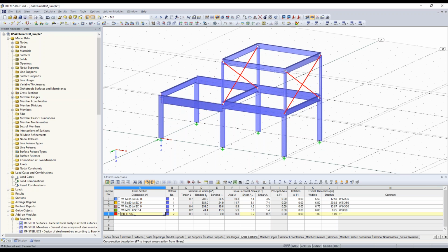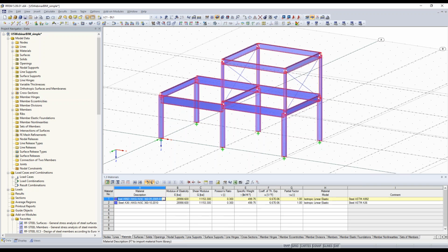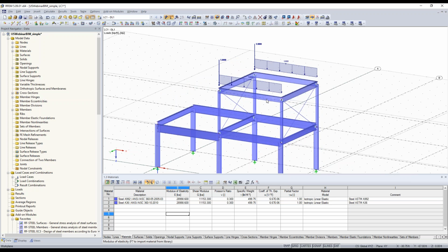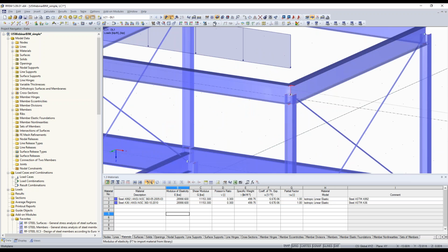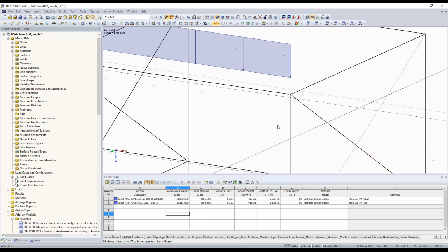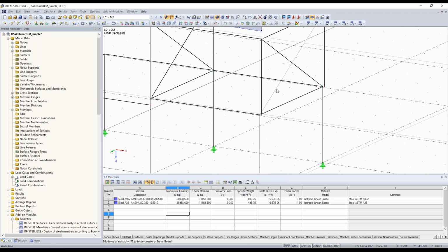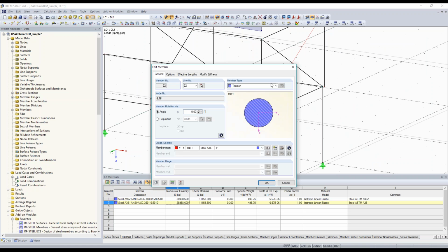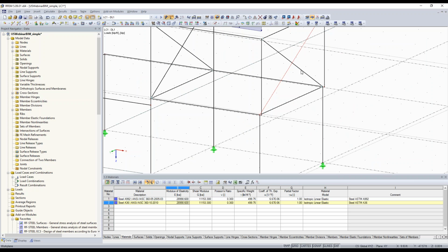So when I look at the materials, also steel ASTM was transferred to steel, ANSI AISC material, and same to ASTM. So with this, in the load case, loads are also here, I can see there's some hinges that have been defined, there's the supports, and also this parameter tension only was transferred correctly to this tension bar, and the other one didn't have the parameter, so that's a beam.